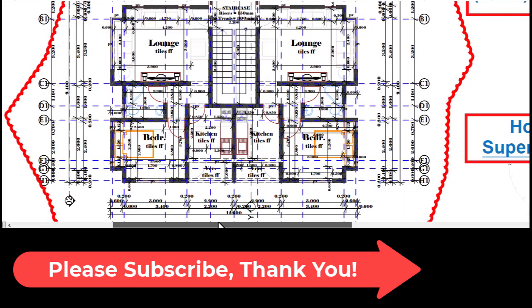Okay, then straight away we switch the grids, and at this time we look at along the grids H1, F1 and so on. I'd like us to start from the bottom where we have H1. H1 is along the external wall, so we are not going to include that in our measurements for the internal walls. We check on G1. G1 followed closely, there is none as an internal wall. F1 as well.